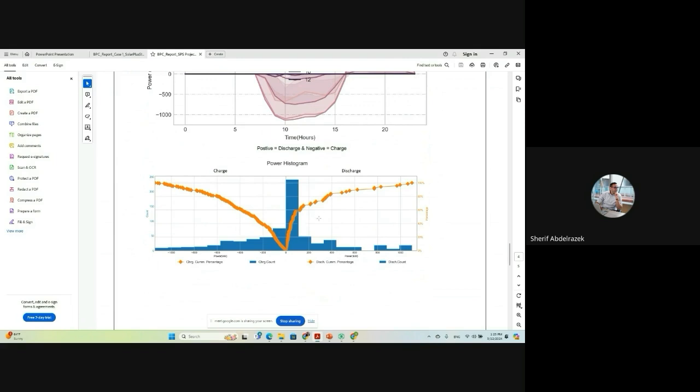An easy way to read a CDF is, you look at a number, so let's just say 600 kW. What's the percentage at 600 kW? We're at about 90%. What that means is 600 kW represents the 90th percentile, right? So what I can deduce here is if I size my system at 400 kW, I can be covering almost 90% of the points. So that's for discharge.